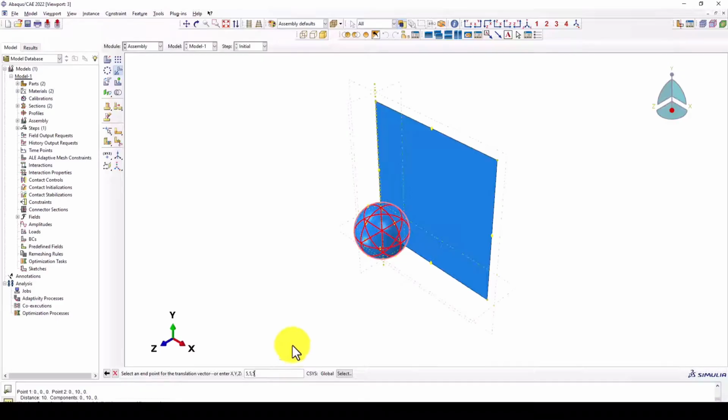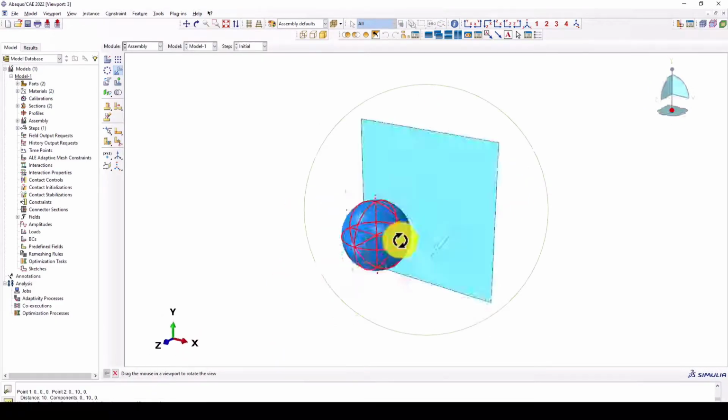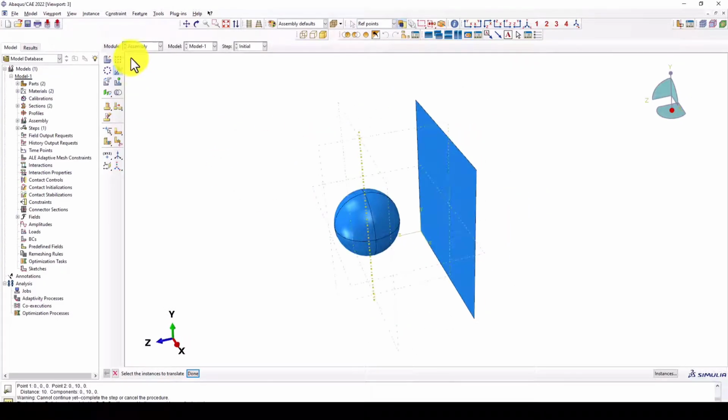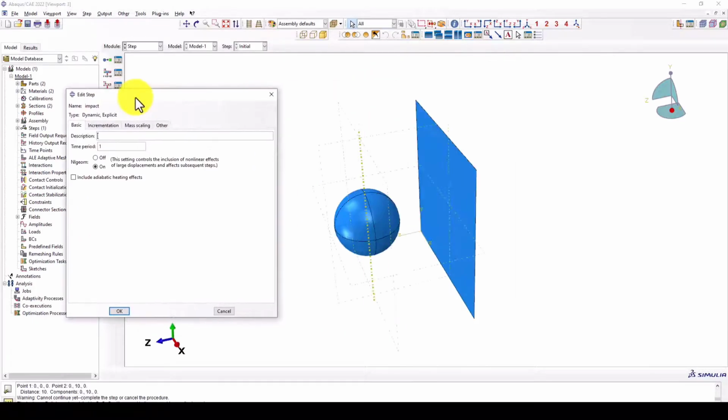Because we are using an explicit analysis solver, it becomes very effective for studying complex contact, large deformation, rapid loading, material failure and severe nonlinearities, with the inclusion of dynamic problems as well. And I told you that modeling choices can very much compensate upon the speed of the analysis. That is mesh size, element type, material density, mass scaling and RBD.